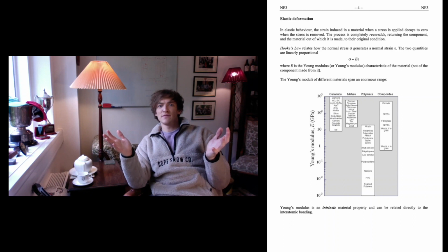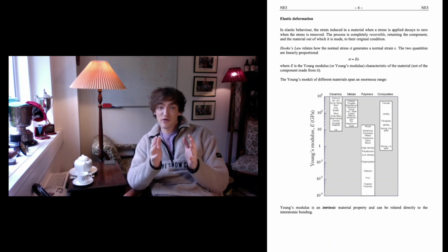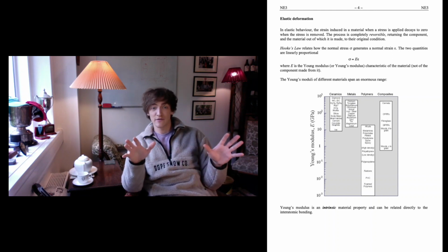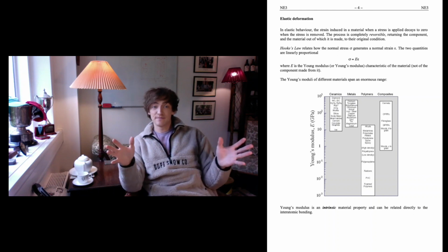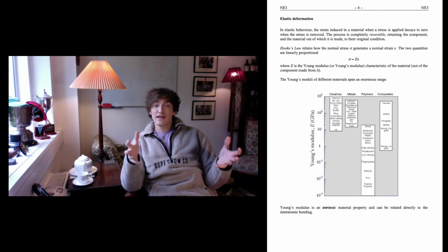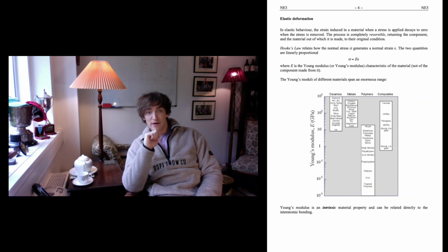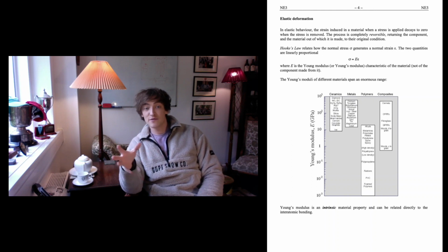Now, you might think, Young's modulus, what is that? Well, the Young's modulus is an intrinsic material property. It's a characteristic of the material and not the component the material is made into, rather. So it's dimensionally independent. And there is a wide range of different materials with a wide range of Young's moduli, as shown in the figure here, with ceramics having a relatively high Young's modulus in comparison to the lower Young's moduli possible for polymers.